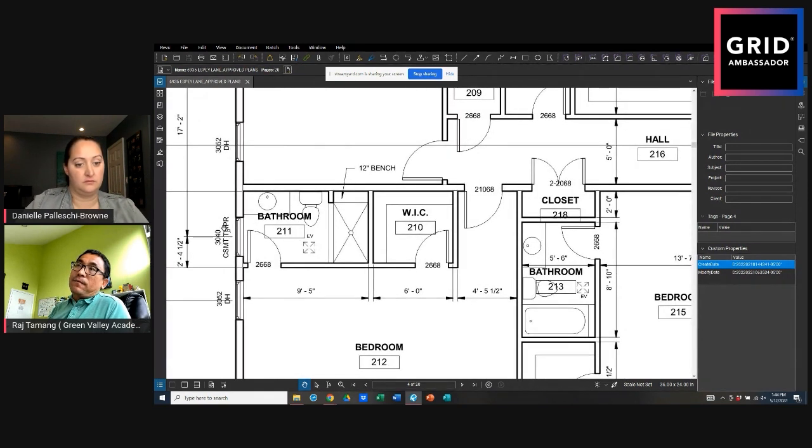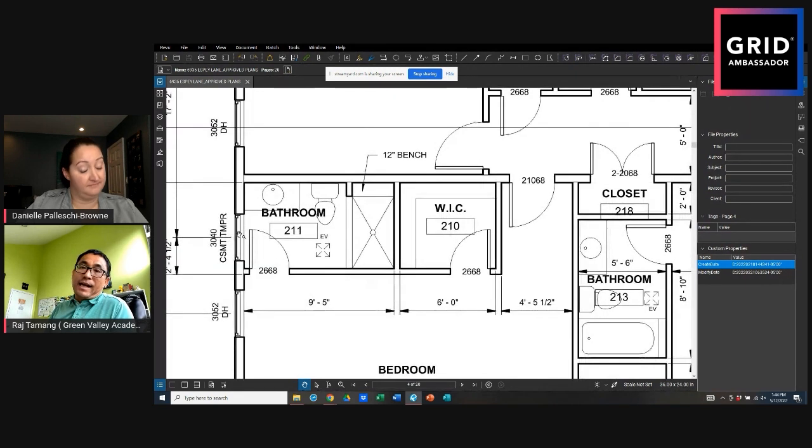And this is 3 foot by 4 foot, 4 foot tall, 3 foot. It's a casement, but I'm doing tempered. It's not necessarily because the window sill is less than 18 inches. The window sill is more than 18 inches from the floor. But you have to think about this door. When you open it, if you are not careful, you may just bang. You know what I'm saying? You may just break the glass.